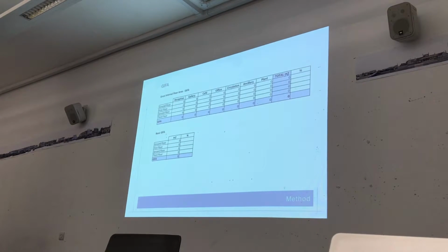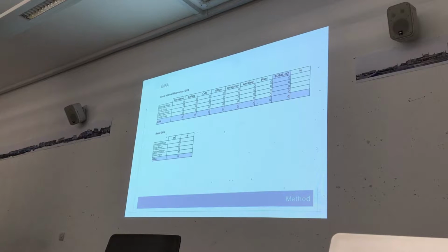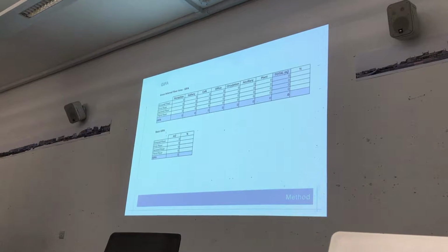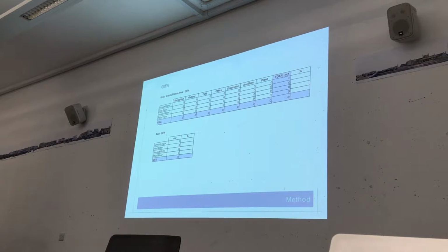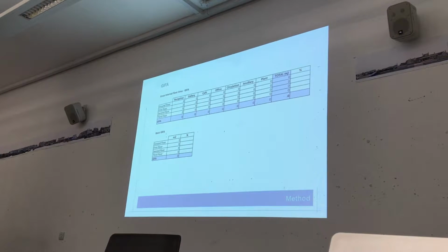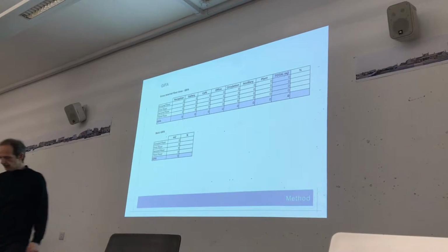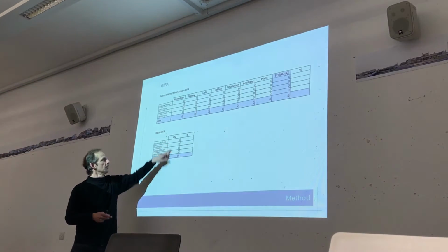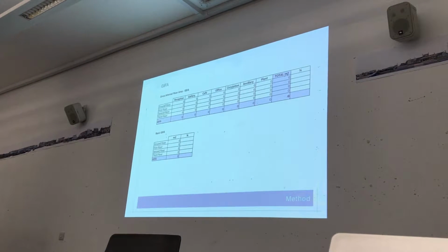So you use the gross internal floor area, and it might be helpful to develop that a bit so you've got the different functions within the building, because then you're probably going to have different finishes on the floor, you're probably going to have different finishes on the walls. So at least if you know what those individual areas are, that might speed it up when you come to putting the figures into the spreadsheet. But otherwise, this is what you've got currently, and you've got a number here. So the spreadsheet, when you put these numbers in here, it should automatically put that, fingers crossed, into the spreadsheet.